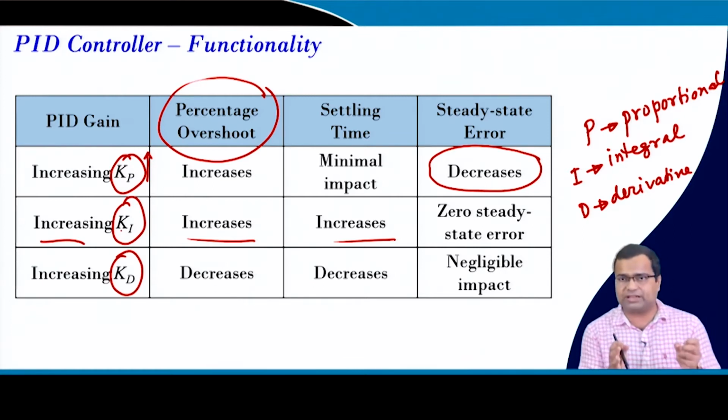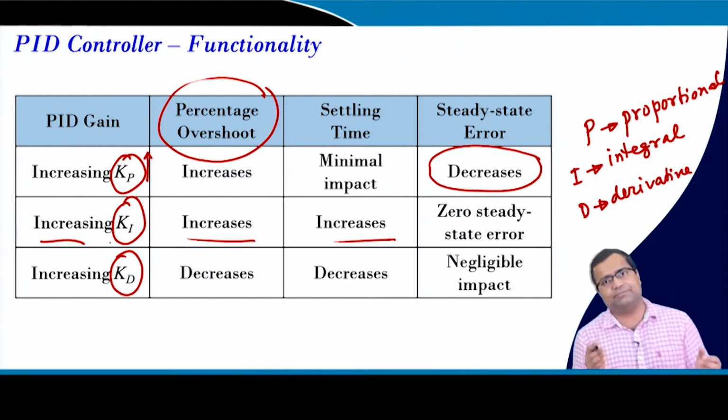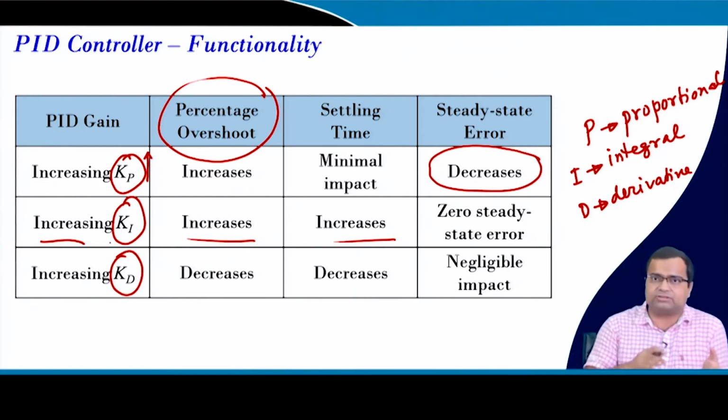But in analog control, we design all these PID controller coefficients offline, so they are designed at the very beginning. But in digital control you can tune them. Nevertheless, if we increase the integral action to reduce the steady state error, it has an impact on the transient response.